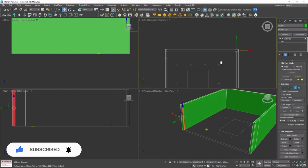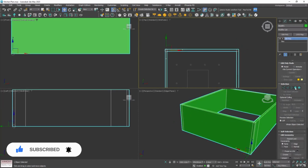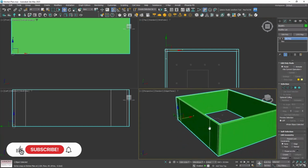A great thing about smart extrude is when we meet another part of the wall, that's actually going to cleanly connect these wall edges. So we can turn off polygon mode, and there we have our walls.